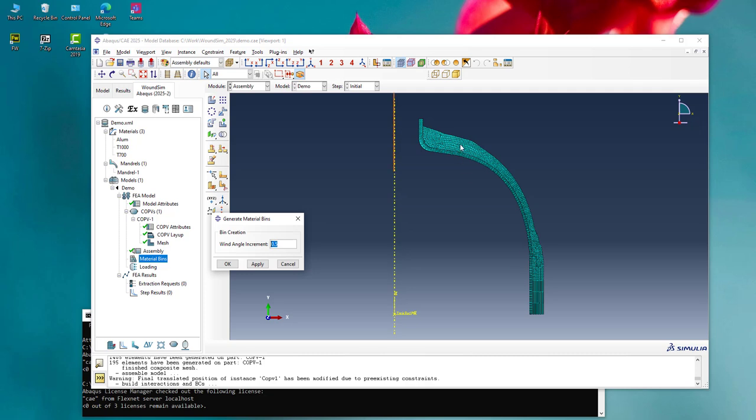So we're going to end up with half-degree bins, so we can break 0 to 90 into 170, 180 different materials. Now the next question is, why do we need different materials? Well, we've entered a material. Why do we need to do anything with that material? Well, we've entered T1000, but that's the material in the fiber direction, and throughout here the fiber direction is out of plane.